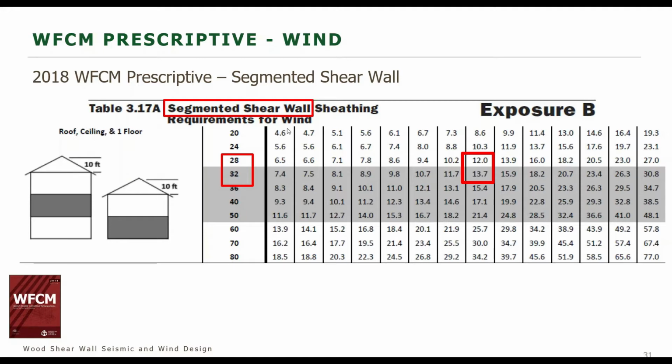Unfortunately, the top part that had the wind speeds got a little chopped off here, but the column we're using is the 130 mile per hour gust column. So you have one for just about every wind contour you might need. We have tables here for exposure B, that's what our building is in, but we do have tables for exposure C as well.